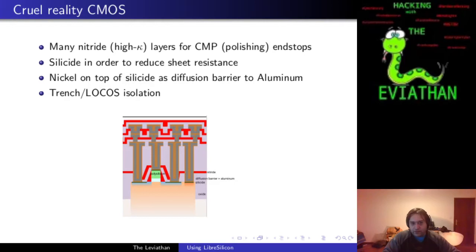While building standalone transistors can be achieved with relatively simple equipment, as soon as you want to start to integrate transistors into something more useful, like logic gates or even further into processors, you need to start isolating logic gates from each other in order to prevent latch-up effects.